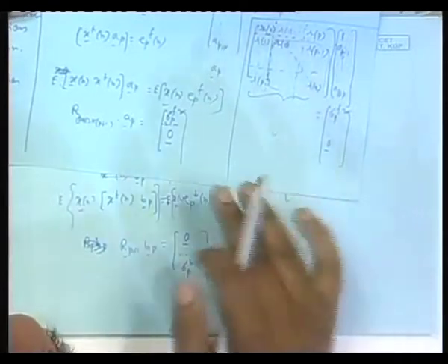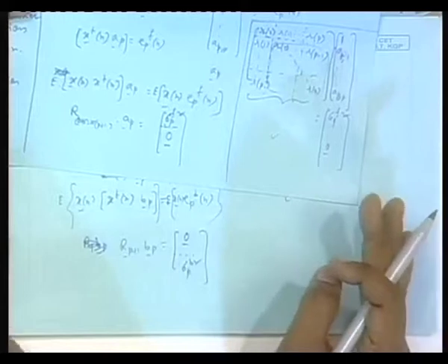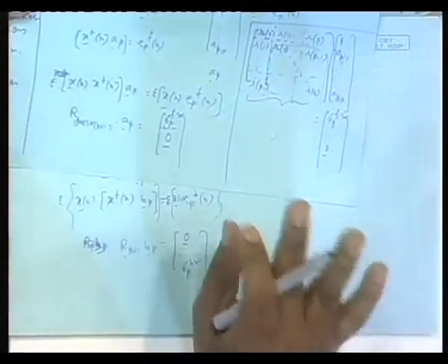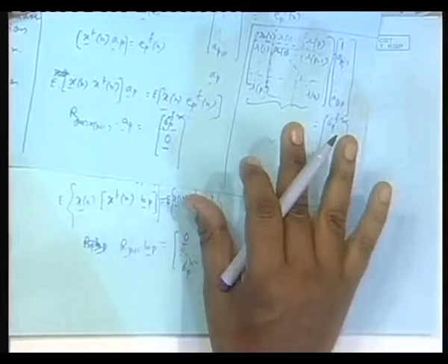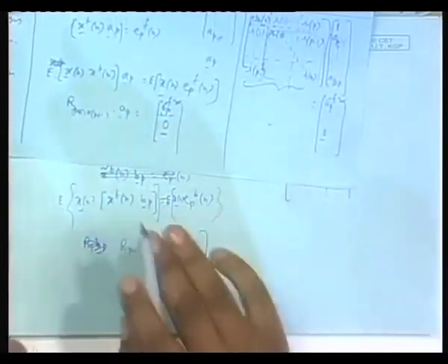So Levinson-Durbin says that instead of solving one equation like this, solve both the equations simultaneously and recursively for various orders. That is what we do in lattice. What we do in lattice is just the algebraic version. That is, if you take out the vector space meaning of all that, and just look at it from the equation solving point of view, then you have that. You simultaneously solve a forward and backward prediction error problem, order recursively.